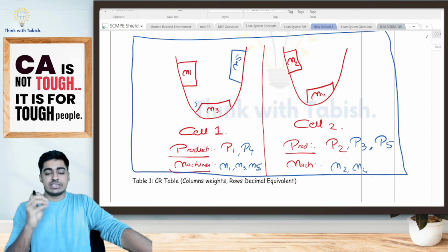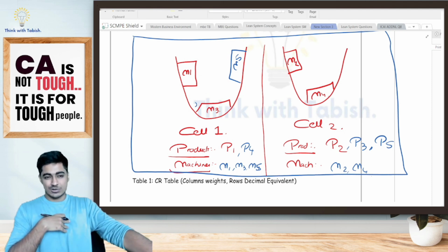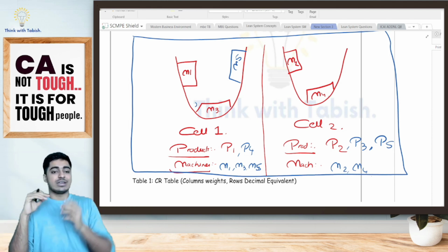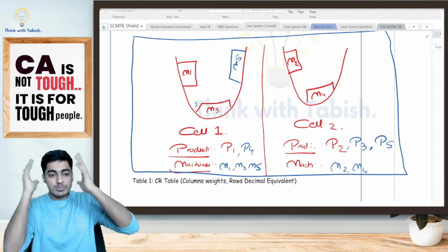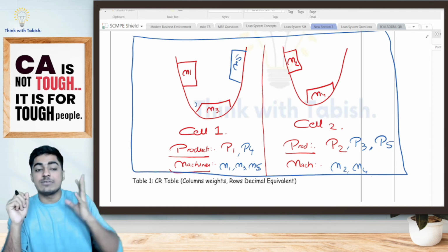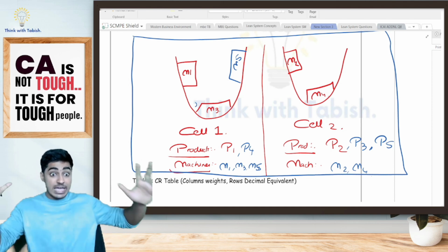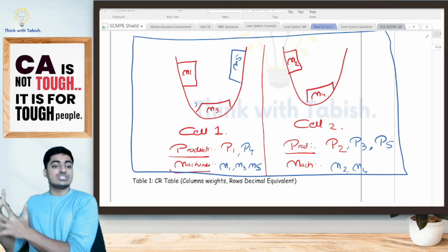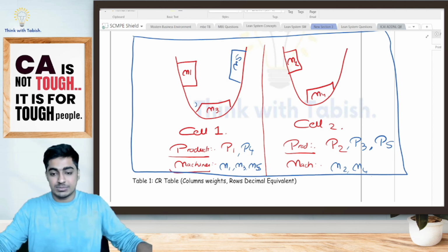No doubts? So, the same answer we want to get using the rank order clustering algorithm. See, when we have only 5 to 6 machines, it is simple. We can manually do it, group it here, group it here. But when the number of machines is more, think of a big organization like Tata Motors. To produce a car, they may want somewhere around 500 components, and they may have somewhere around 200 machines. Now, how do we arrange those machines in a systematic way? This is what our ROCA, rank order clustering algorithm, is telling.